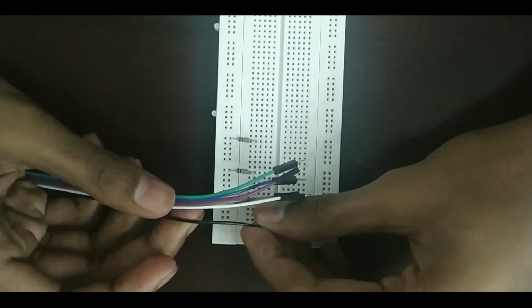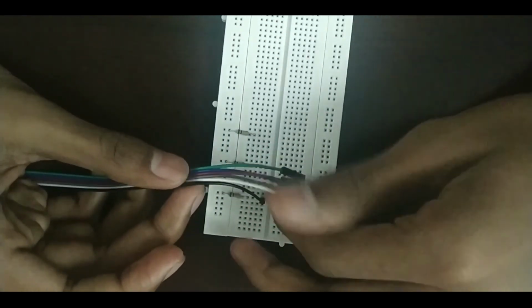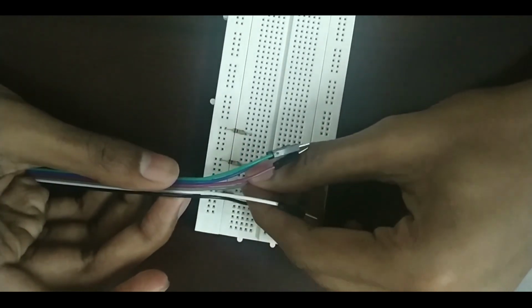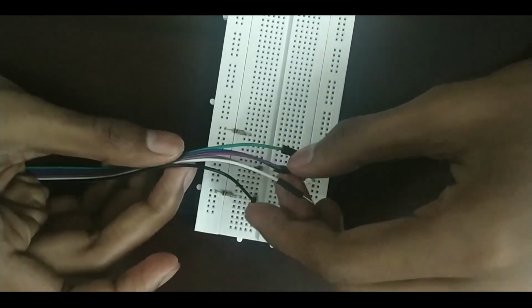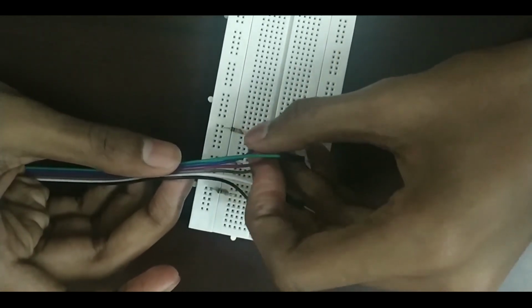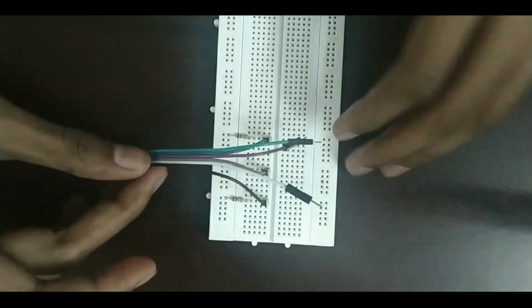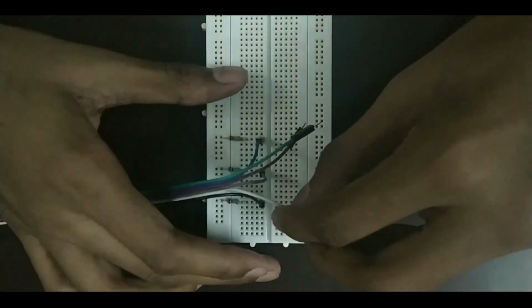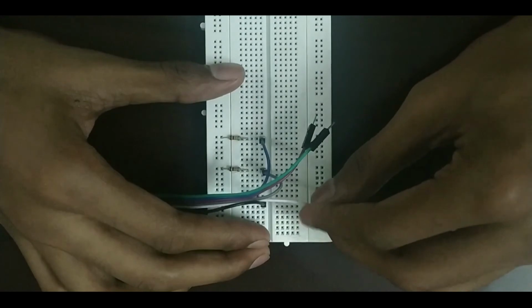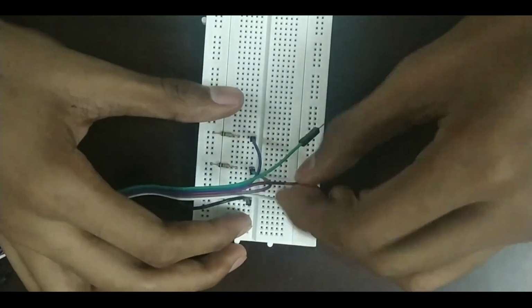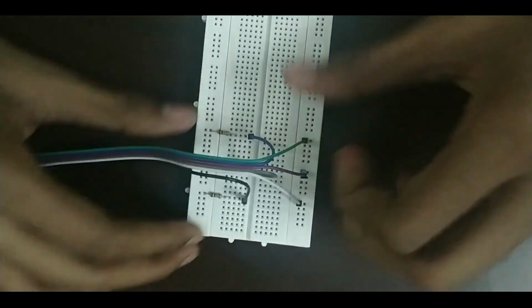Each flex sensor has 2 terminals. Connect one to the ground and other to one of the columns we have connected our resistors to. Connect these terminals in a way such that one pin is empty in between the terminal pin and the resistor.